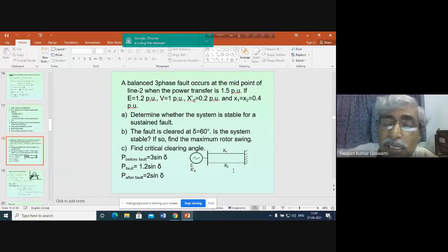the line, obviously in long transmission lines here, okay, important transmission lines, these are high voltage lines carrying hundreds of megawatt of power. Perhaps I forgot whether I have actually mentioned the power transfer capacity of a line. If say this is a long line, say the voltage is 400 kilovolt, then the rated power is around 600 megawatt.